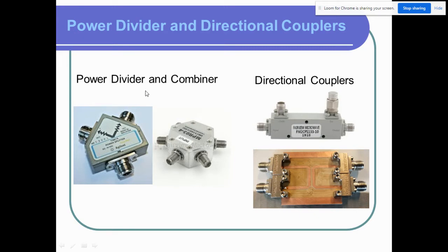In a similar way, this one splits the power. If you give different frequency or same frequency signals here with different power, it will combine this power and give you one output. So that's why we call it a divider, and also we call it a combiner.